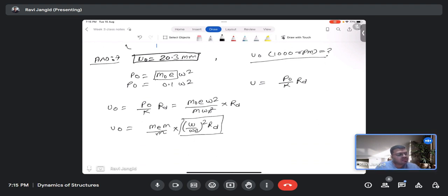So how do we get it? Like you are saying, I will put the RD as 1 over 1 minus that value? Yes, yes. There only the damping ratio is there. But I don't know if omega n is known. Omega n we can find out, yes, because we have the EI value and the other terms. So we can find out omega n for the beam. Yes, you can try with that.